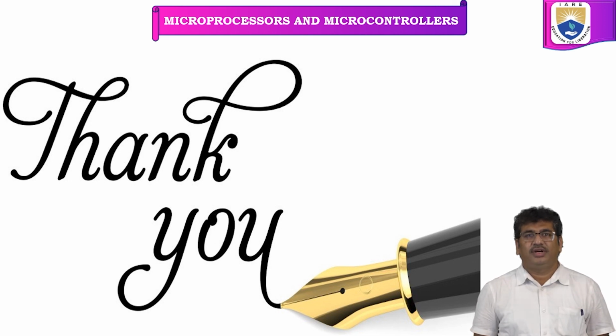So in this lecture, we have discussed what the 8251 is and what the features of the 8251 are. The 8251 is a USART. What does USART stand for? Universal Synchronous Asynchronous Receiver Transmitter. How the data will be transmitted through the USART as well as how the data will be received by the USART. We have studied the architecture of the 8251. We have discussed the pin diagram, and the signal description of the 8251 is also studied. Then the various control registers of the 8251, like the mode instruction register, command control register, and status register, and the bit description of each and every register, we have discussed.